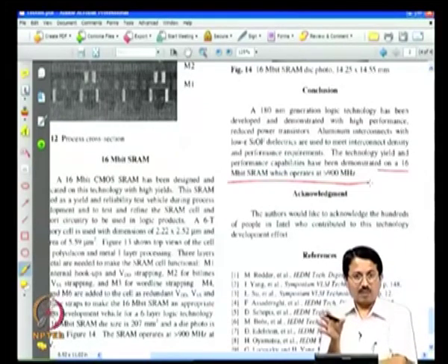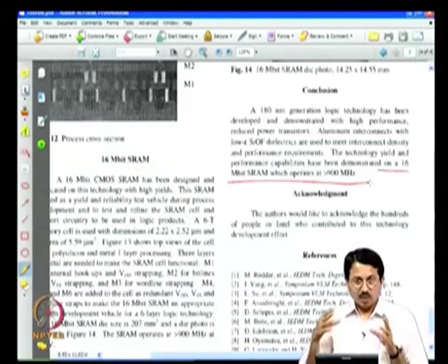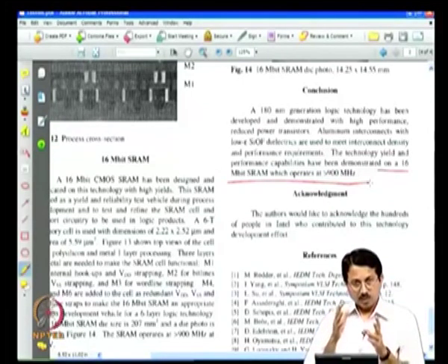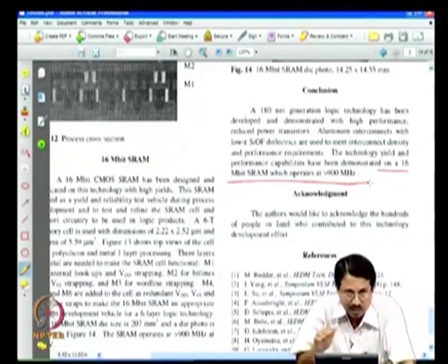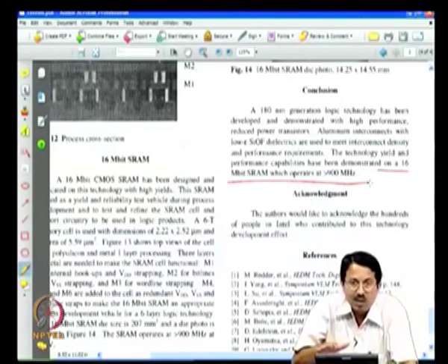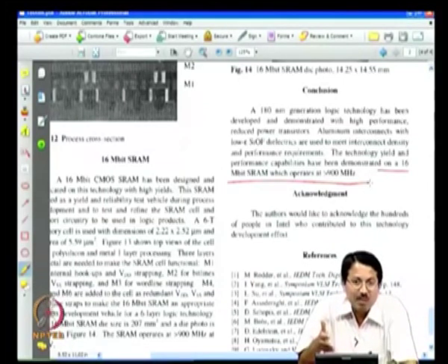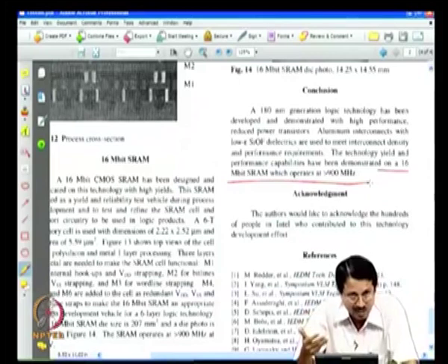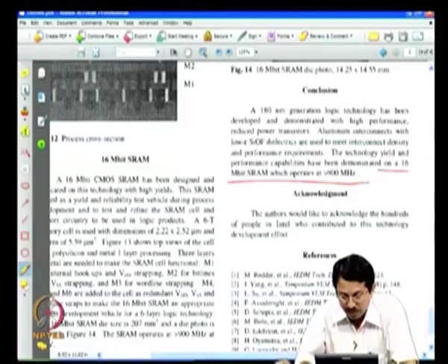So, they have been able to start from the basic semiconductor processes, use all the process integration, build the transistors, demonstrate a simple circuit like a ring oscillator, characterize the gate delay, and take it forward to make an SRAM cell and show that the SRAM is working. So this is really a demonstration of a technology, but after this it may take another year for you to make a real product, because your real product is going to be a microprocessor subsequently. Then you will have to make a microprocessor and make sure that the yield is good, and that requires a lot of optimization.